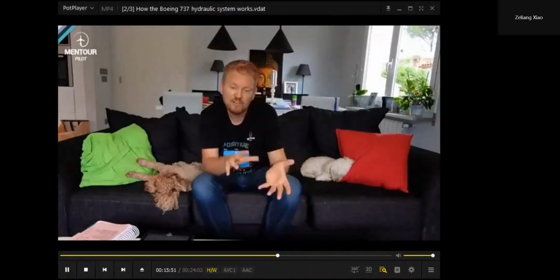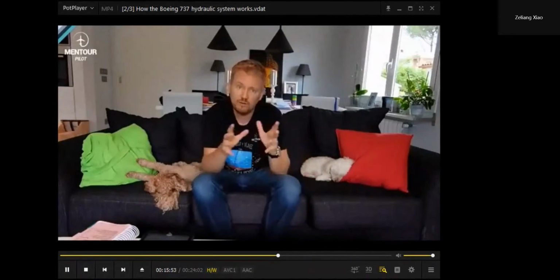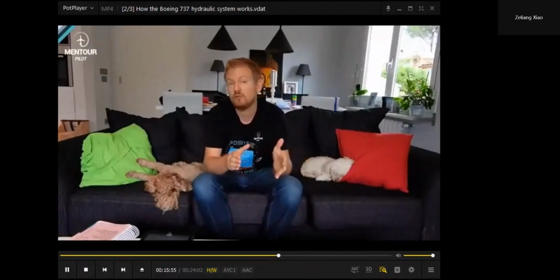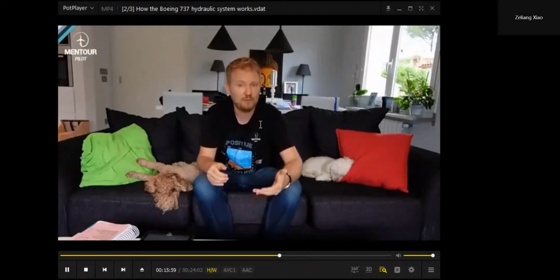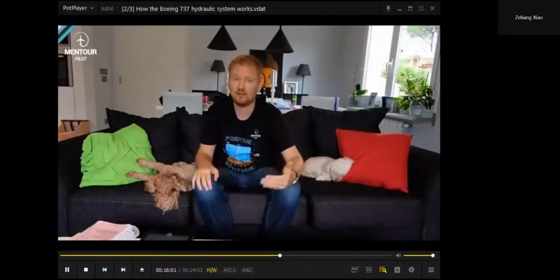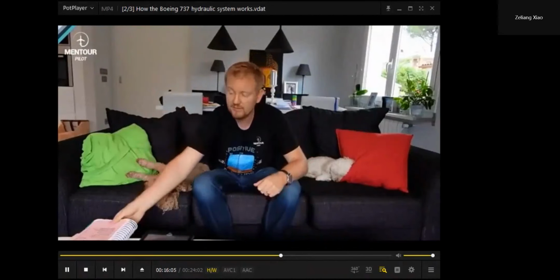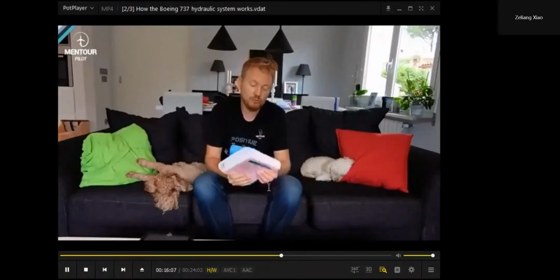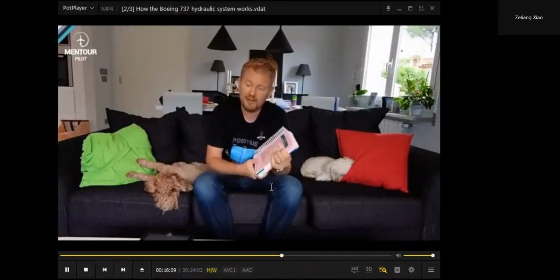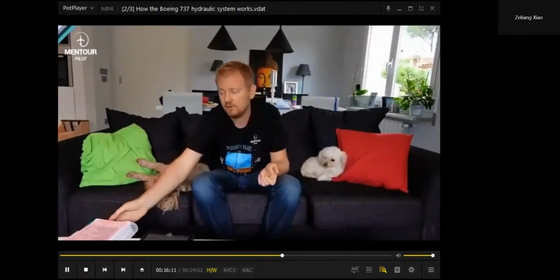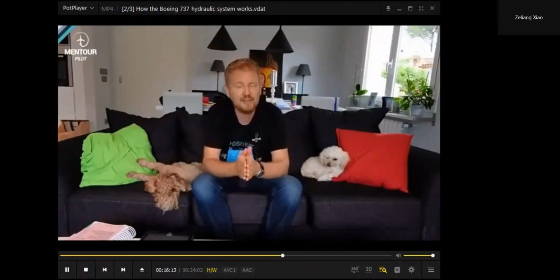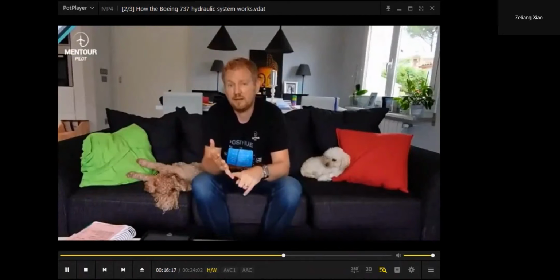And then you have specific parts of the system that will not be activated hydraulically. So in the case of a loss of system A, for example, you'll be able to continue to fly the aircraft perfectly. You just use autopilot B instead. But then as the pilot monitoring reads through and executes the QRH checklist, there are some things that will be highlighted. For example, you need to plan for a manual gear extension.